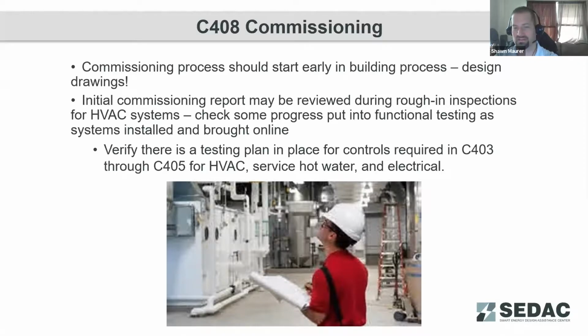And a lot of facilities that I've worked at that were under construction, this was kind of an as completed process where they commission those systems as they're brought online. Although I've also seen it done for smaller buildings where it's kind of a lump thing. Once everything is up and running, then the commissioning is done as a lump project. So it just depends on the complexity and the size of the building, which path is going to be most beneficial as far as saving you time overall and completing the project.